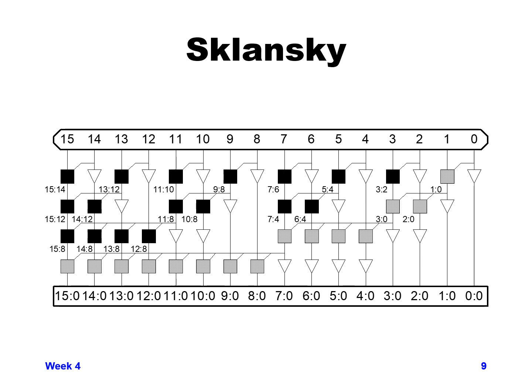When you get to stage 5 though, stage 5 is driving 3 things, and stage 9 is driving 3 things. When you go down for stage 11 for 11:8, after you go down 2 stages of the black squares from bit 11, that second black square is now driving 11:8. It's basically having to drive 5 different receivers.